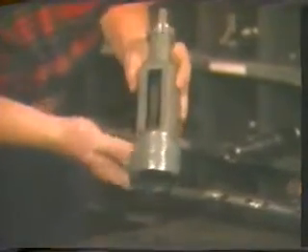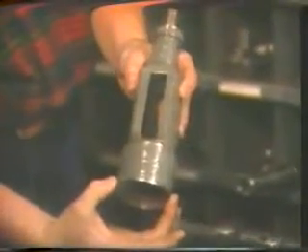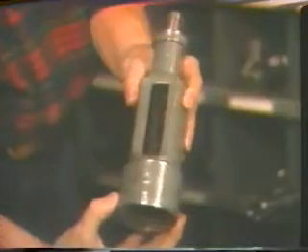The tubing gauge cutter is normally run prior to any other wireline operation to check that the tubing is free of obstructions. These gauges are normally slightly smaller than the minimum ID of the tubing to allow the gauge to pass through the tubing but stop if any obstruction is encountered in the tubing bore. These gauges are beveled to remove paraffin deposits or light scale deposits from the tubing wall.